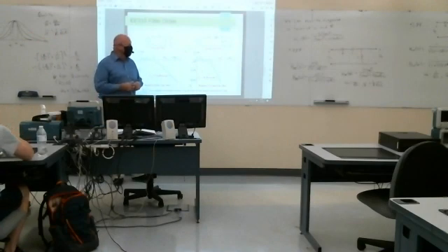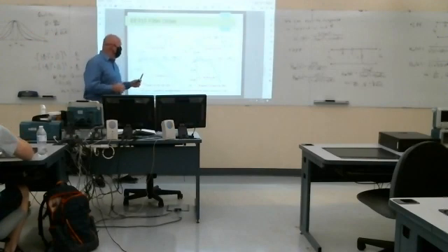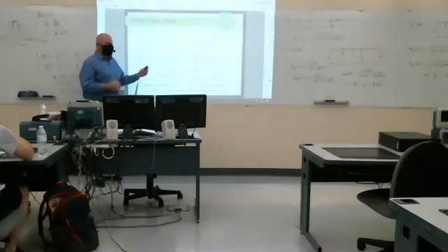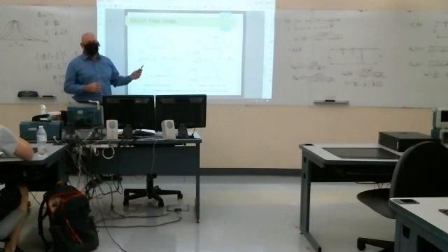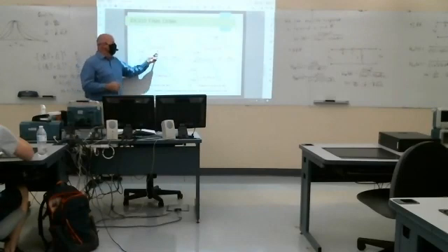It's difficult to get an inductor on a printed circuit board as well. So there are trade-offs. Certainly, if this is good enough and cheap enough, depending on the application, this first order filter may be sufficient.